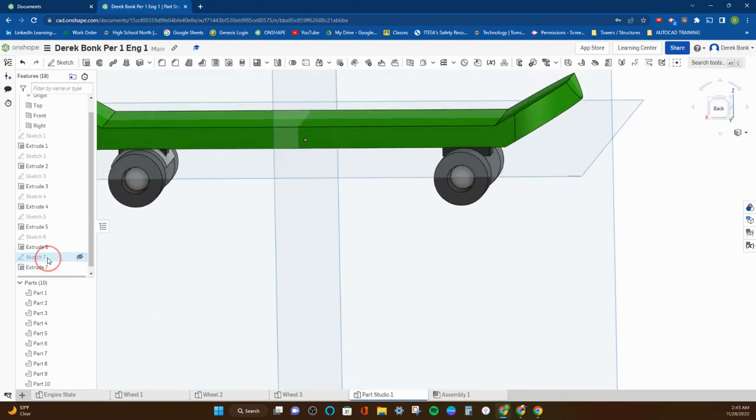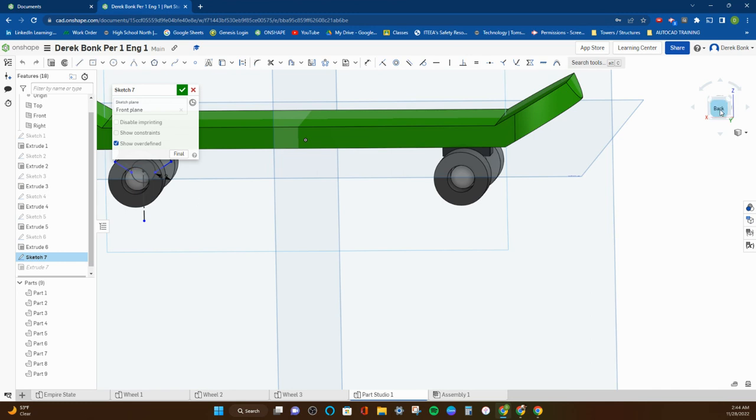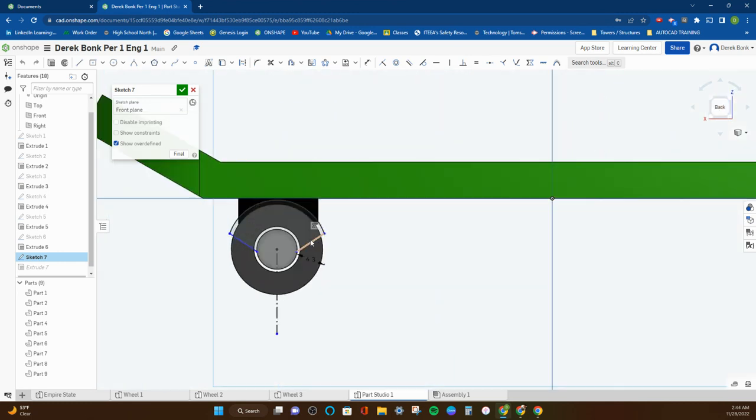I'm going to go back into the sketch. I like what I just did. And I just created, I know that was difficult to follow, but we'll get there. I'm going to mirror this. Now I had to click the mirror line. Now I'm going to click what I want mirrored, and I'm going to click this, this, this, and this.